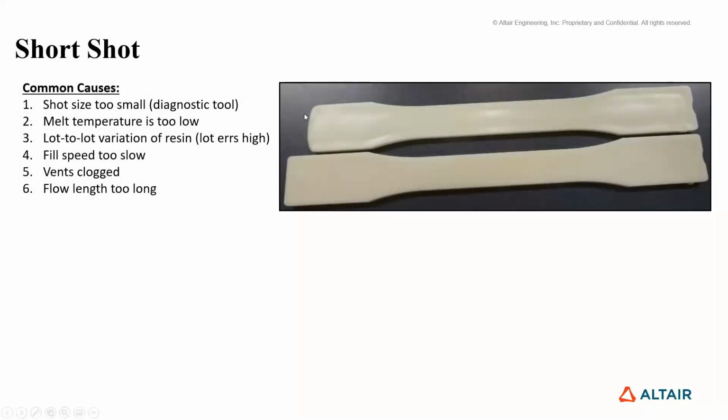So short shots, right? You can see here one part's full, one part not so much. You'll also see some effects like this edge, this little sink around the edges of the part. That's a real thing. We're just starting to catch that. I don't have a model queued up to show you the edge effect, at least not one that I can show you. I have one in a model that's proprietary, unfortunately. But I'm starting to see this edge effect going on in my simulations.